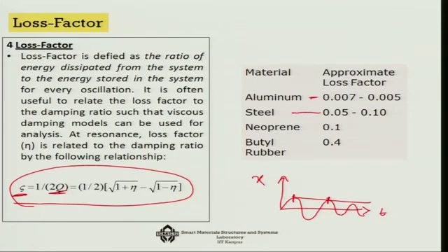And if you look at rubbers, which are generally used as damping materials, they have a much higher loss factor, an order of magnitude higher. That says why we use rubber or neoprenes etc. as damping material, unlike the metals. Generally polymers have much larger energy dissipation, and hence eta is much more for the polymers.